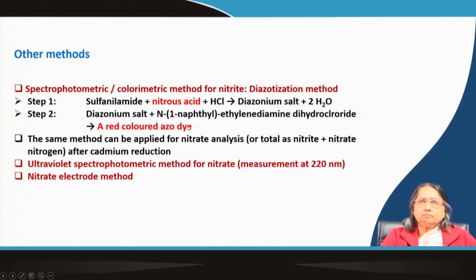So, ultimately this is the colored compound that will be formed, and you can measure the absorbance in the spectrophotometer. So, basically it is a very quantitative method, you can use it. The same method can be applied for nitrate analysis or total as nitrite plus nitrate nitrogen after cadmium reduction.